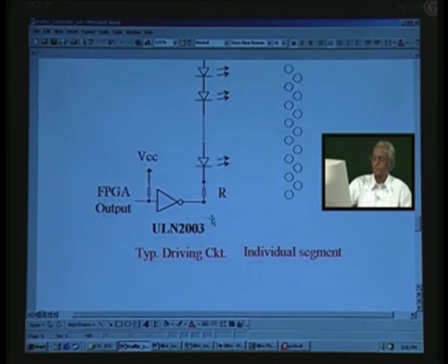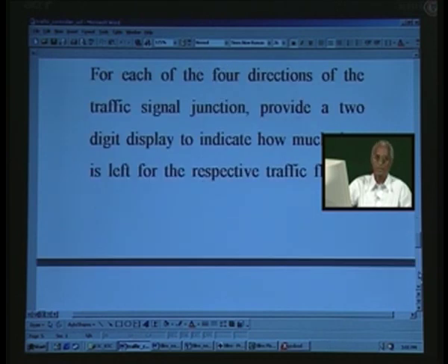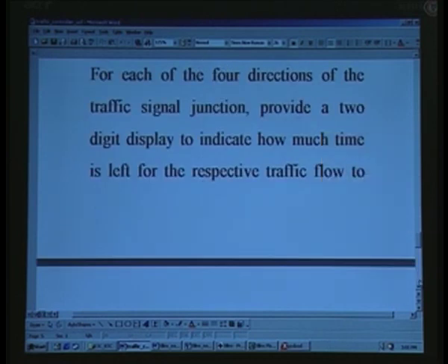And suppose instead of an LED you want to drive a solenoid or relay, say a solenoid, you can go right up to 500 milliamps. So you can use this same circuit for some other purpose. To drive a solid state relay, you require a different setup, which we may see in future.